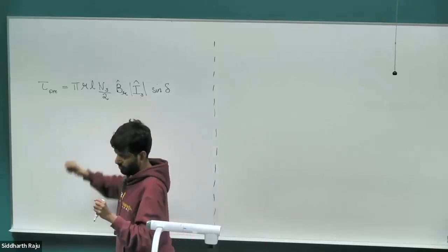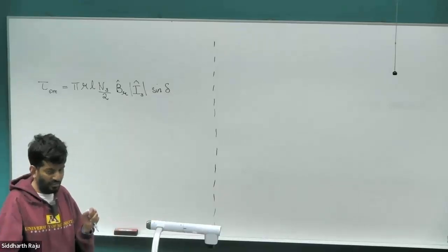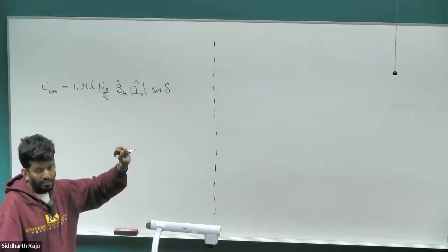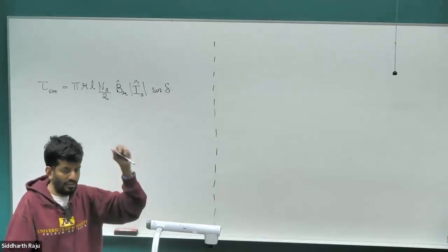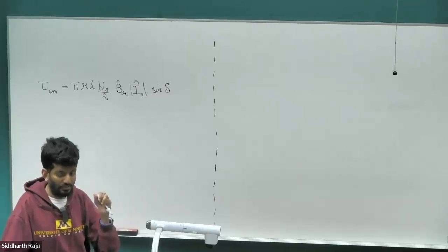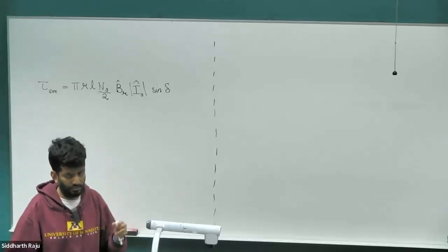Again, for the stator current space vector, we have looked at multiple interpretations of what that means. None of them physical. In the sense of the conductor distribution, we figured the stator current space vector points to the direction where the conductor density of all three phases combined would be at its maxima at any given time. Right, N times I product for all the three conductors combined together, carrying three sinusoidally phase shifted currents.